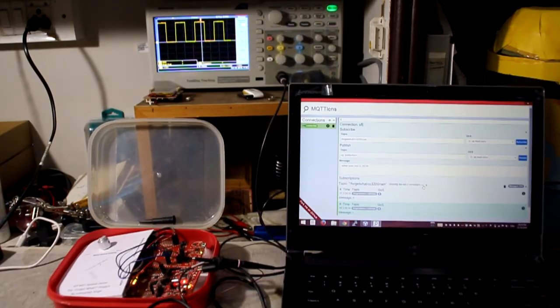The next module is the CC3200 based MQTT system. Now this is a true IoT system wherein the CC3200 is transmitting to the internet to iot.eclipse.org to port number 1883.